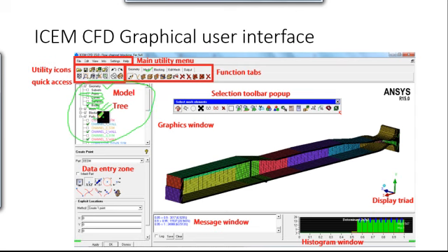And you can create the different parts with the help of the part menu. You just right click on this menu and you will get the first option is create new part. And if you uncheck any part, the mesh of that part won't be exported. Also, the parts are very useful to define boundary condition. Otherwise, you are not able to define different surfaces with the help of the different boundary conditions if you don't define the parts. So parts are also necessary to define the boundary conditions for the solver.